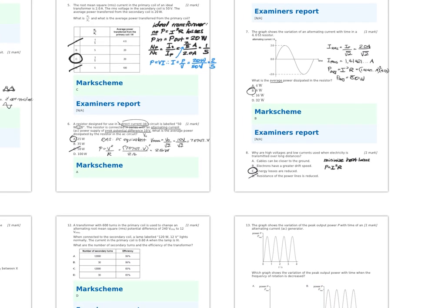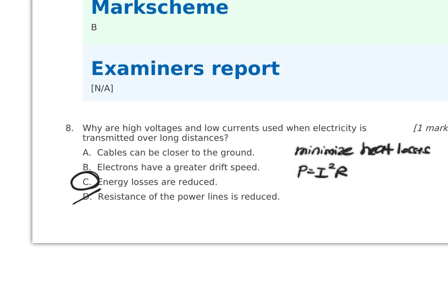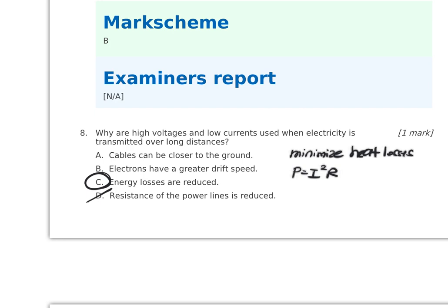Yeah, we want to reduce energy losses by having, one other point. What does reducing energy losses have to do with high voltage, low current? It's the current that causes heat. That's the thing that's actually causing the heat in the wire. The more charge flow you have in there, the hotter it gets because of the collisions between the charges and the structure of the conductor. So by reducing the current, that's how we reduce the energy. We're not reducing the power per se because P is VI. So by bumping up V, we reduce the current, and that's how that works.